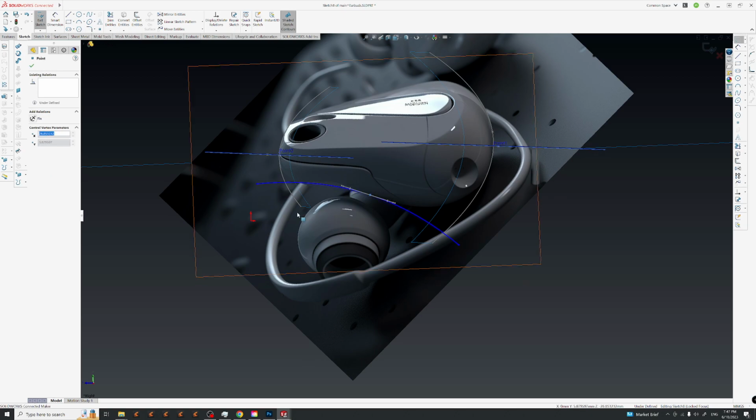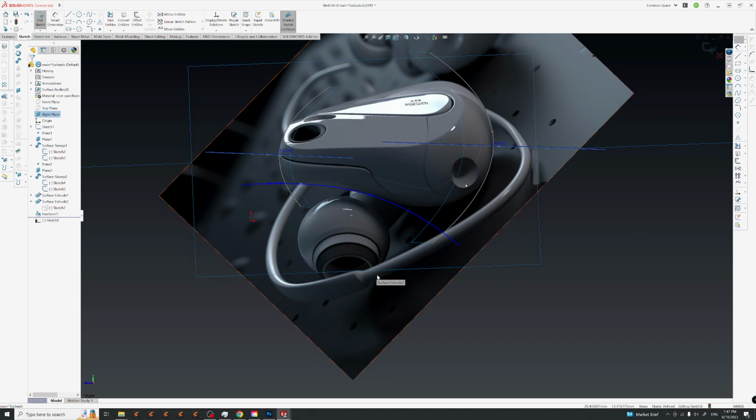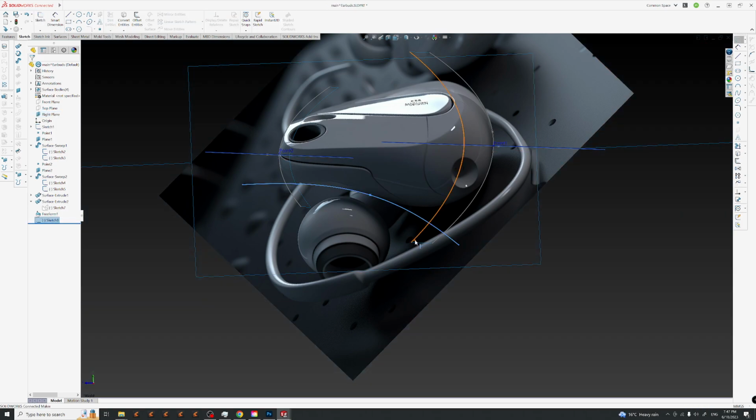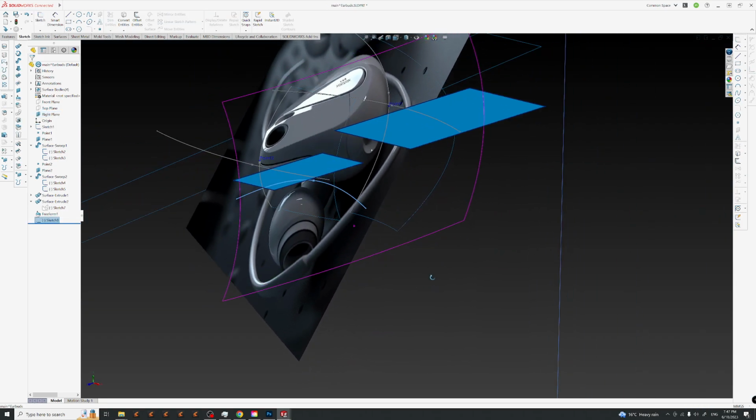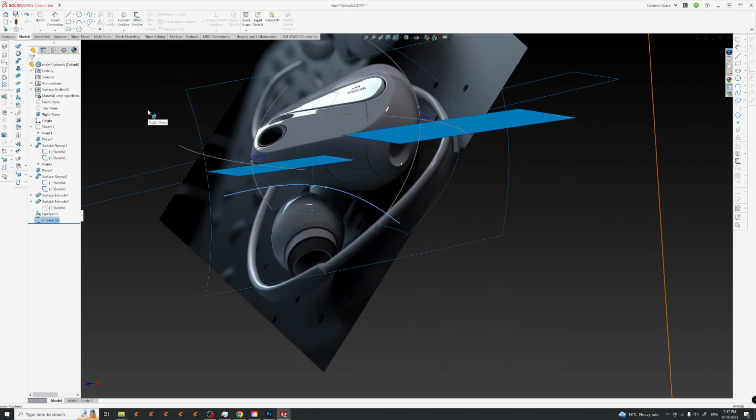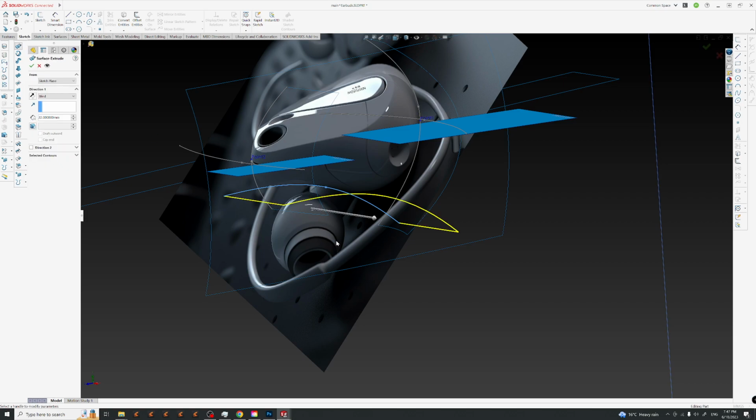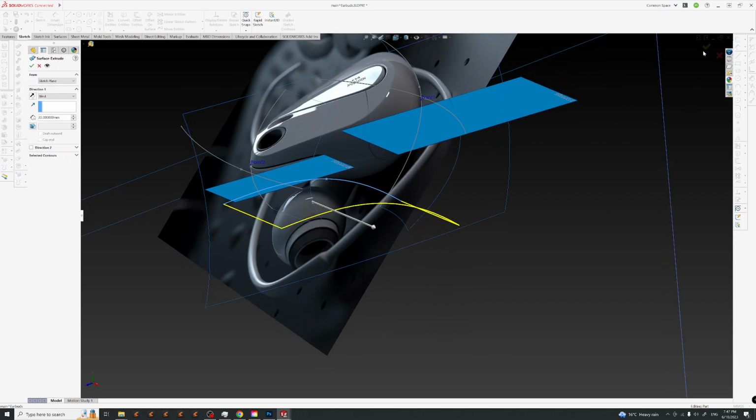So that means we will have two splines that will compose the surface. Now, again, we will apply the same principle as before. We will just update the surface directly rather than creating two splines to create the surface. So let's extrude this. Yeah, I'm fine with that.